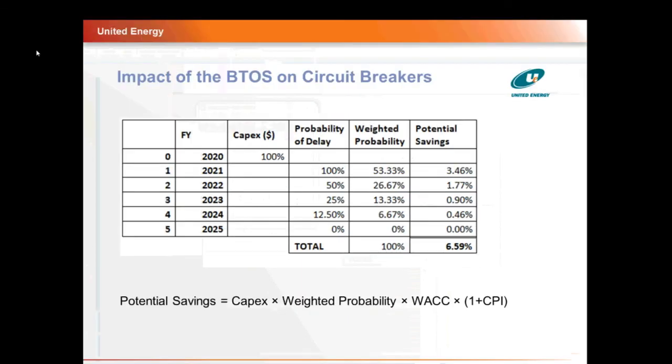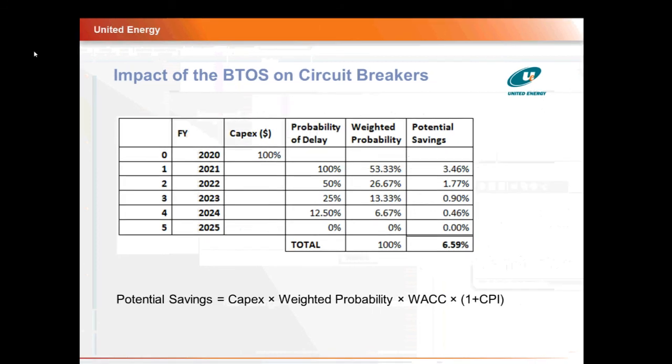On the other hand, we know that the fault current in the feeder and in the faulty bus greatly reduces, and the benefits of this can be seen in circuit breakers. We know that with circuit breakers, the asset life is dependent on the total number of operations and on the fault current that they trip. So if the bus tie open scheme operates and reduces the fault current, this would also reduce the breaking duty of the circuit breakers and hence increase their asset life.